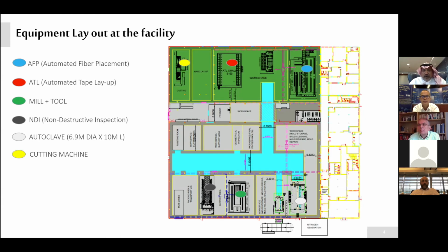So you have to control pressure, temperature, and particles for cleaning. It's a positive pressure inside the clean room to push any dirt or any sand or anything outside the area, so nothing comes in, because it has to be very pristine in order to make a composite part, as you may all know. It has to be a very, very clean area, especially at this build-up time.